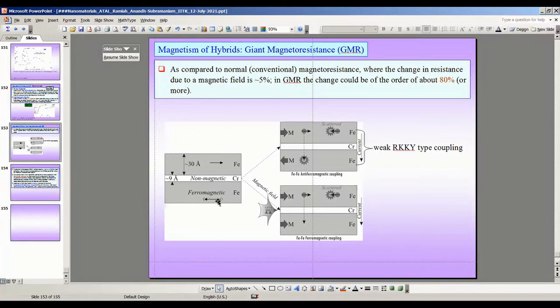But when it enters the second layer of iron, all the magnetic moments of the atoms are located in one direction. And in iron, the preferred direction is the 001 direction. There is a strong scattering of these, but this scattering is coming not from thermal scattering, not from impurity scattering. It is coming from spin-related scattering. It's spin-driven electron scattering. And this leads to a high resistance state.